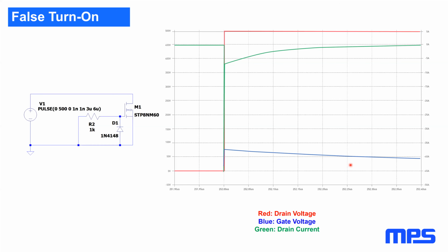Okay, next one up, is it possible to destroy a gate with too high of a gate current peak? That's an interesting question, and I've never really thought about that. I've never heard of it happening. I suppose at some point, yes. There's things like bond wires inside the device that are limited in how much current they can take.